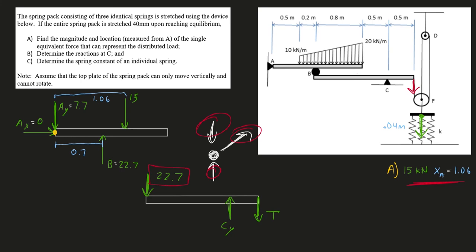You'd really have to analyze this joint right here, do some forces x and y, and figure out what each one of these individual things are. So I always recommend just watch out for situations in which your junction or your joint has more than two elements in contact with it. But in this case, we're safe with that 22.7.